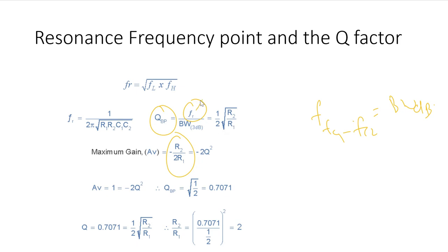If the center frequency is low and the bandwidth is high, we have a low quality factor. If the center frequency is high and the bandwidth is low, we have something like this. It is a notching effect, and it is of high quality factor. High quality factor means that we will have a very sharp cut or sharp rise in the frequencies.